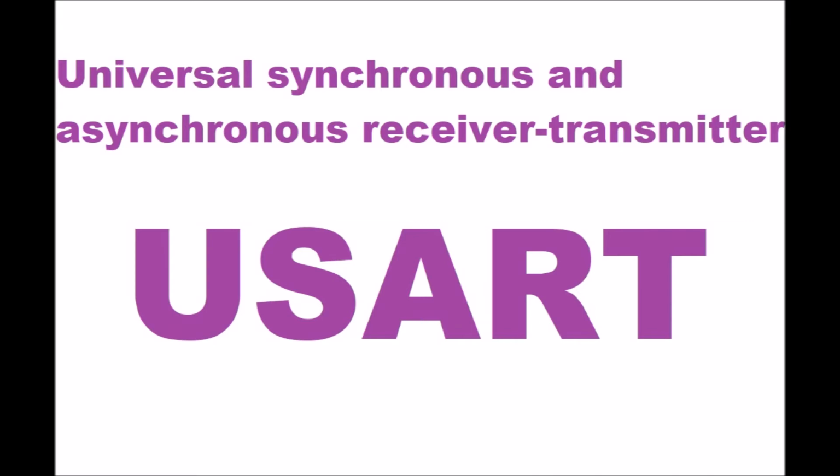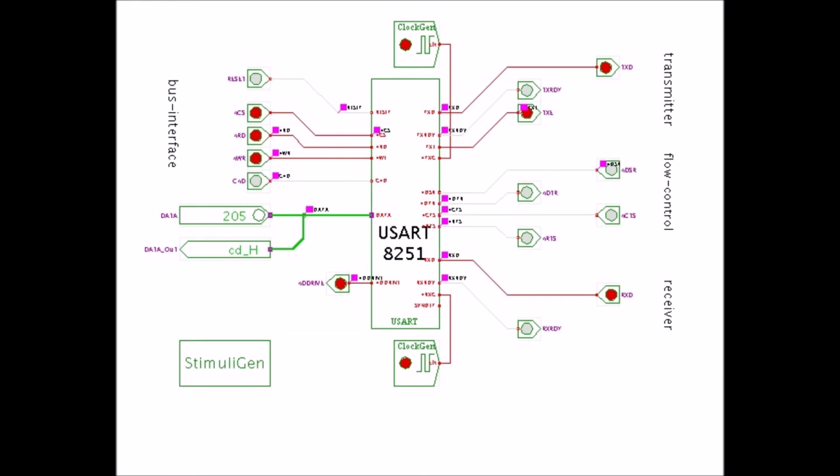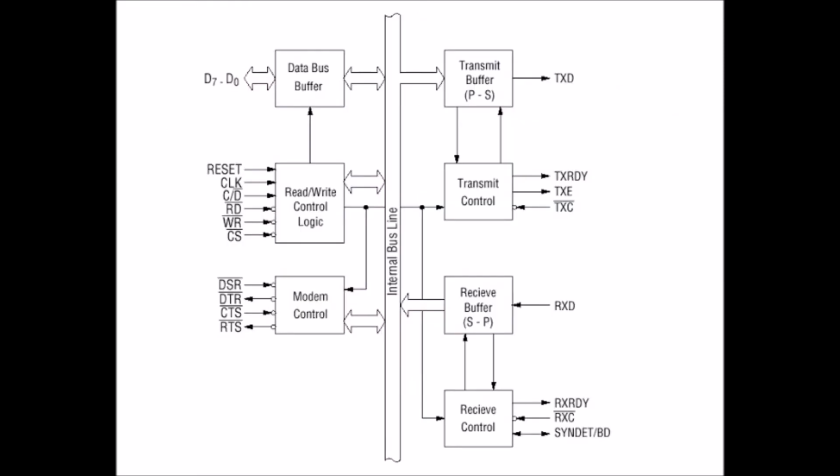Purpose and history. The USART's synchronous capabilities were primarily intended to support synchronous protocols like IBM's Synchronous Transmit Receive (STR), Binary Synchronous Communications (BSC), Synchronous Data Link Control (SDLC), and the ISO standard High-Level Data Link Control (HDLC) synchronous link layer protocols, which were used with synchronous voice frequency modems. These protocols were designed to make the best use of bandwidth when modems were analog devices.